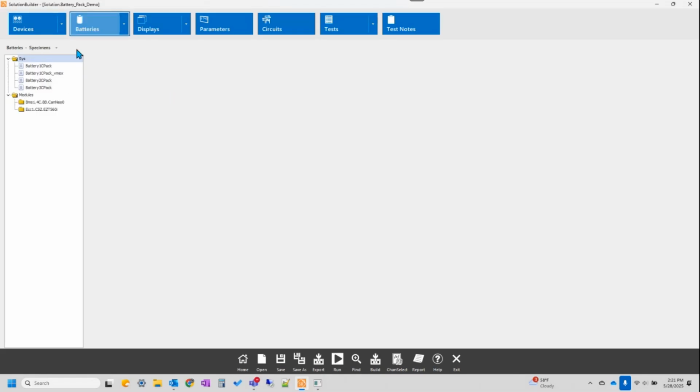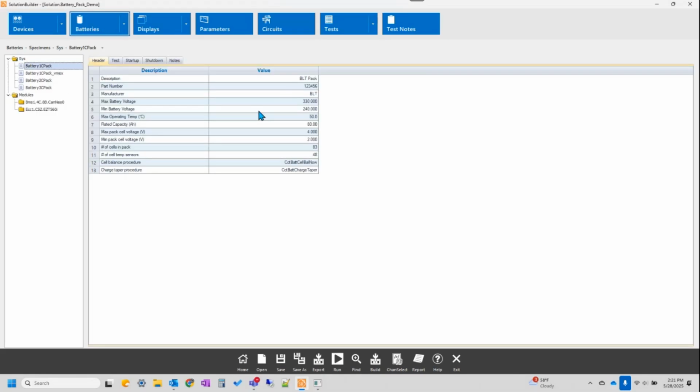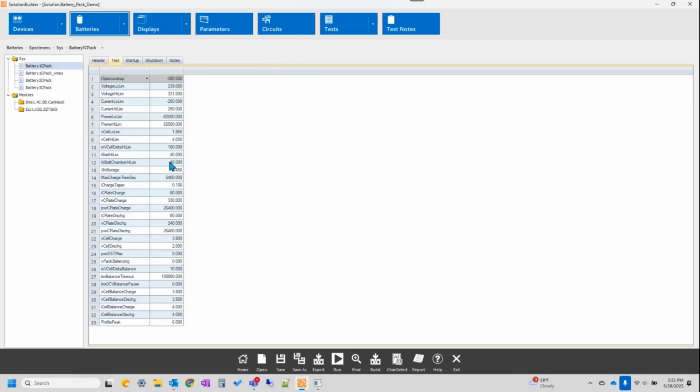iTest.BTS uses a battery specimen file to drive everything for testing batteries. This file contains all the data about the battery itself, like minimums, maximums, and it also contains the test environment or the test requirements like low, high, and cell voltages. Because iTest.BTS uses this battery specimen file, each of the schedules that are used to test the system can be utilized to test virtually any battery simply by changing the listings, data, and parameters in the specimen file.